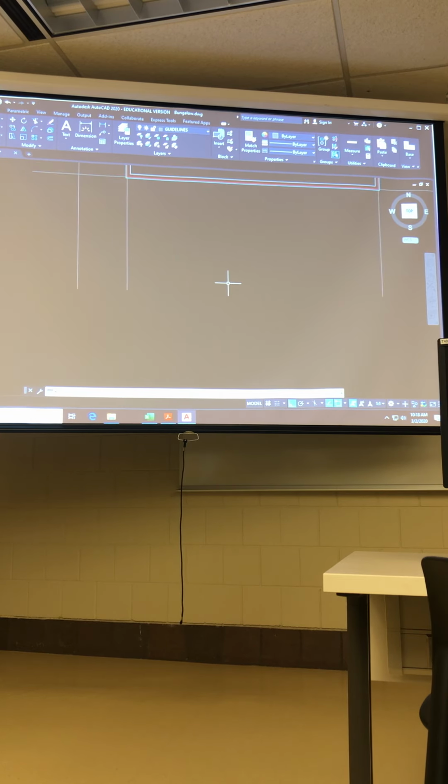And once I have all of those datums in place, my vertical guidelines for the wall locations, my horizontal guidelines for the floor levels, I can start to create my section drawing. So just like we did with the floor plan, lay out guidelines that locate structure first. That's where we begin. So let me get started.